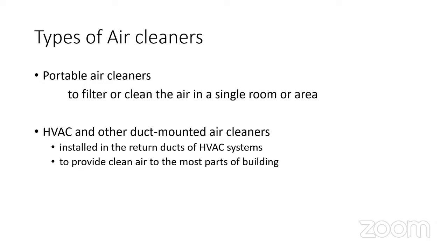In some of the portable air cleaners, beyond the filtration and sorption, further technologies to increase pollutant removal, inactivation or conversion are also used. Then ultraviolet lamps are sometimes used to inactivate the biological contaminants in the space. That will also be discussed further in coming slides.